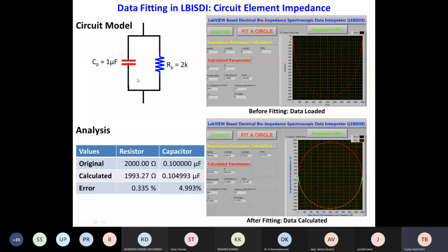That means the 0.1 microfarad will have some larger value and lesser value also. So that was not the accurate one itself whenever it is manufactured. So no resistor or capacitor is found with 100% accuracy. So there is always tolerance, and the capacitor that was used, 104 capacitance, that is 0.1 microfarad, was also having some errors.